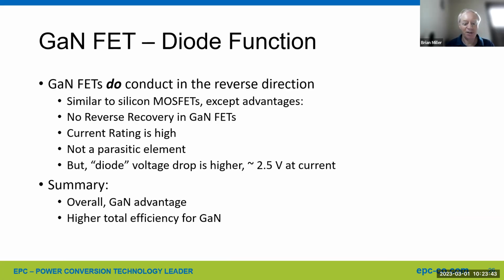Okay, changing topics just slightly. The question comes up also with GaN FETs: are there diodes? Do you have to put an external diode around it? How do you deal with dead time with a GaN FET? And the answer is nice and convenient. GaN FETs do conduct in the reverse direction. It's very similar to silicon MOSFETs in function, except there's no reverse recovery in the GaN FETs in the diode mode.